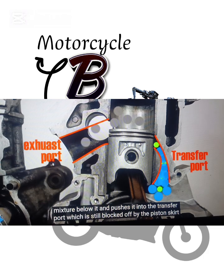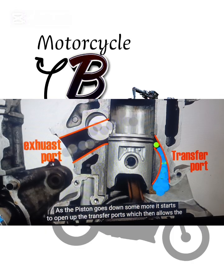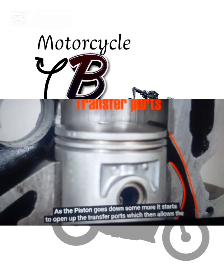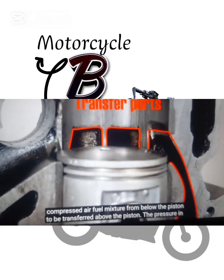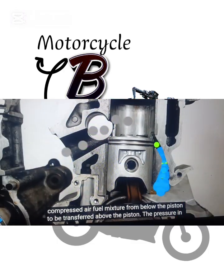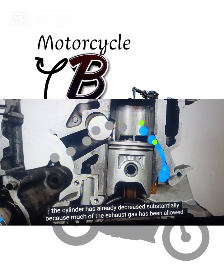As the piston goes down some more, it starts to open up the transfer ports, which then allow the compressed air-fuel mixture from below the piston to be transferred above the piston. The pressure in the cylinder has already decreased substantially because much of the exhaust gas has been allowed to escape through the exhaust port.